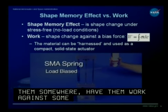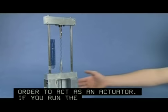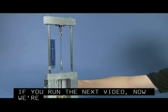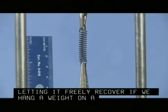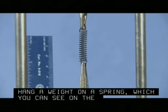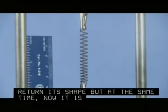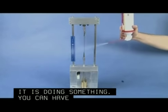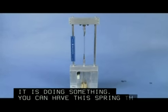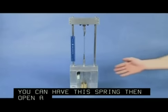in order to act as an actuator. For example, if you run the next video, now we're going to go back to the spring, but instead of just letting it freely recover, if we hang a weight on the spring, which you can see on the bottom, and you heat the material up, it'll return its shape, but at the same time now it's pulling a weight, so it's doing something. You can have this spring then open a latch, move something, and then as you cool it back down, the weight de-twins the material and pulls back the spring.